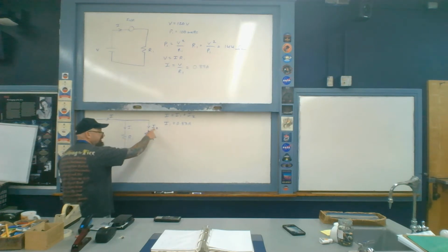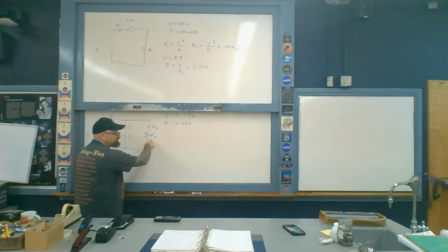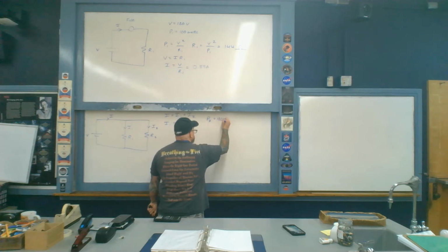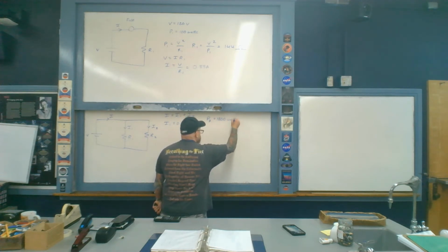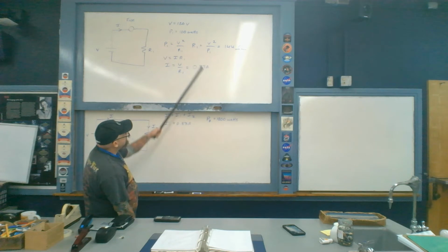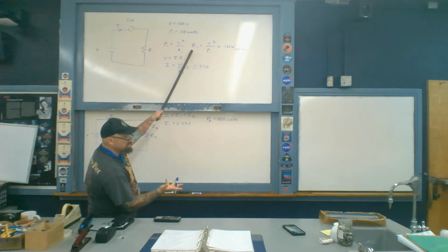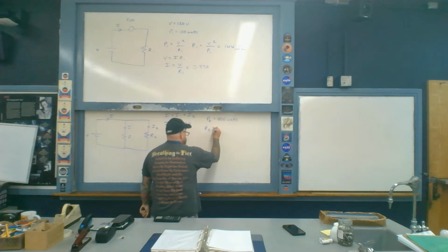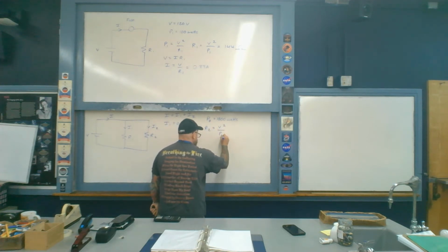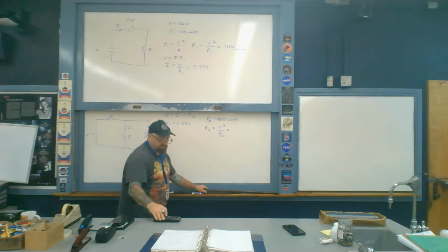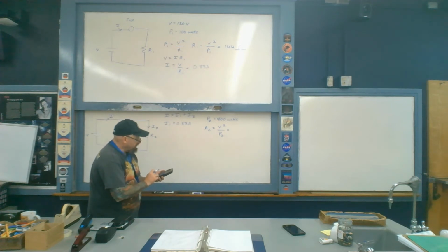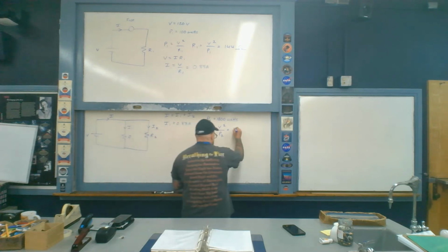But now we also have current here flowing through the electric space heater. So now we have P2 for the space heater is given to us as 1800 watts. And now I'm going to go ahead and calculate the resistance. We'll call it R2 across the space heater by using this expression. So R2 is the same voltage squared, but now divided by P2, like so. So then therefore, 120 squared, and then divide that by 1800. And this comes out to be 8 ohms.